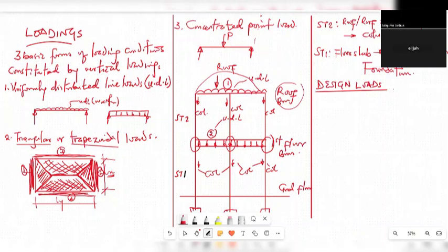To obtain the design load, we usually apply the factor of safety for loads. I will multiply it by the values of the dead load, and we also multiply it by the value of the live load. So, in expression, this is what I mean. The design load denoted as N is equal to 1.4, which is the factor of safety, multiplied by the dead load plus 1.6 multiplied by the live load. All right. So where did we get these things?